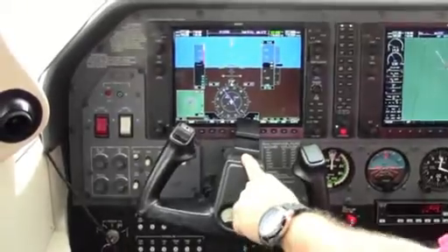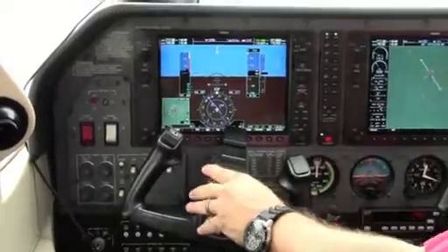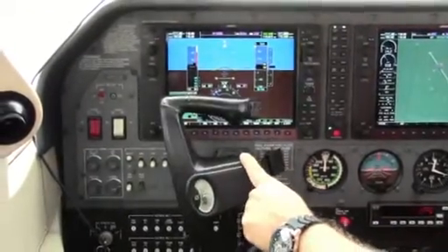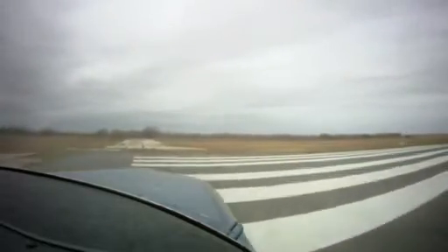It's always preferable to take off directly into the wind when this is possible. However, sometimes the circumstances will indicate otherwise. So the pilot must be familiar with the techniques that involve a crosswind takeoff. The technique used during a crosswind takeoff is almost the same used in a normal takeoff, except that the aileron control must be held into the crosswind. This will allow the aileron on the upwind wing to be raised, imposing a downward force on the wing to counteract the lifting force of the crosswind, preventing the wing from rising.